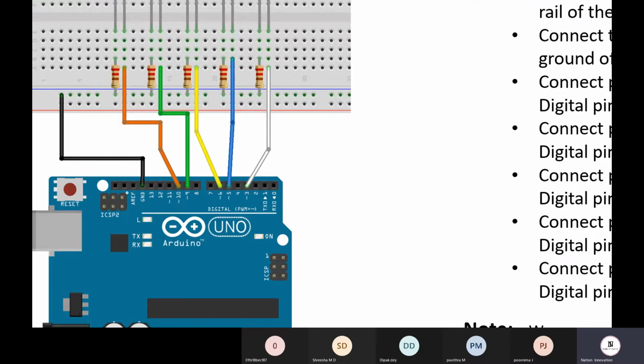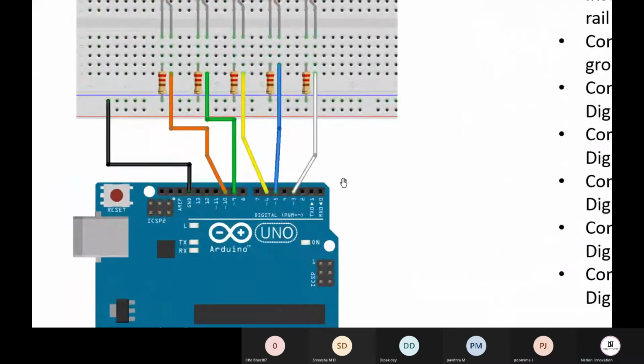And in the coming lectures, I might be avoiding pin number 0 and 1 for the use of this LED functionality. We will be coming to that reason as well when we interface multiple devices, why I usually avoid using pin number 0 and 1. Other than that, if you are just going to use the LEDs, then pin number 0 to 13, you can use anything. Fine.